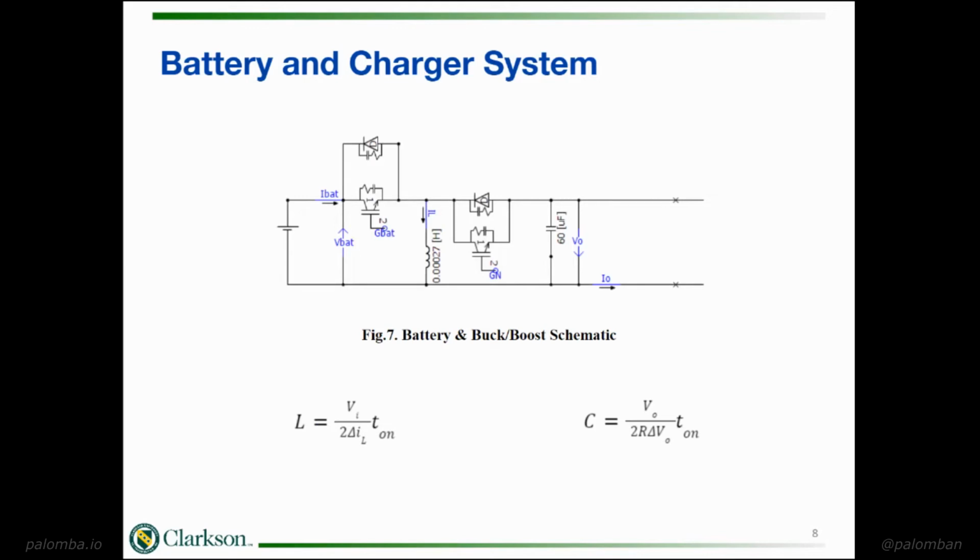We also sized our battery for a 12-hour duty cycle of off-grid operation, particularly during the nightly period of 6 p.m. to 6 a.m. And we simply size this by sizing the system for at least 600 kilowatt hours, which is 50 kilowatts times 12 hours.